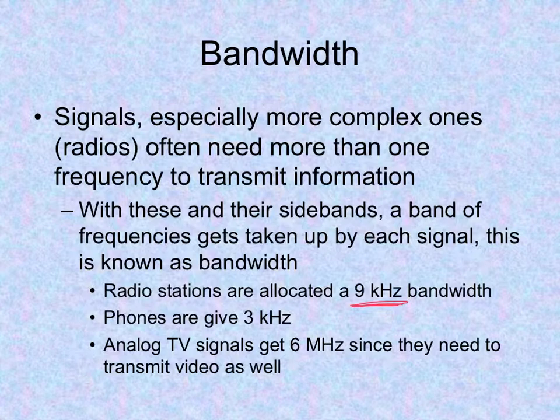And so it's important to realize then that that's why you have to have some distance between the frequencies of radio stations. When you're turning the dial, it's not going to go from 98.5 to 98.6 or AM 550 to AM 555 and have two stations that close to each other, because there would be that overlapping of the sidebands, which would cause interference in the signals.